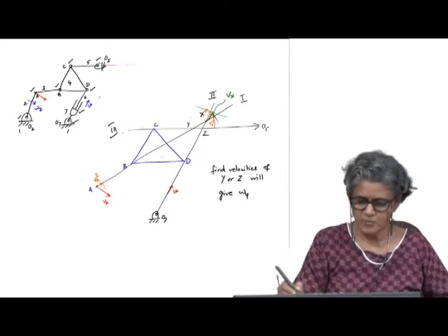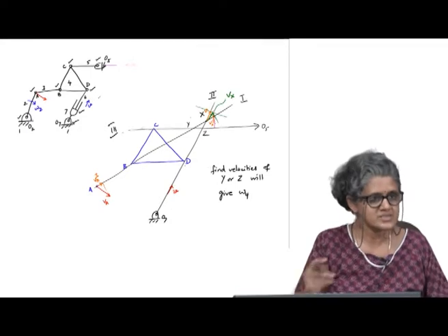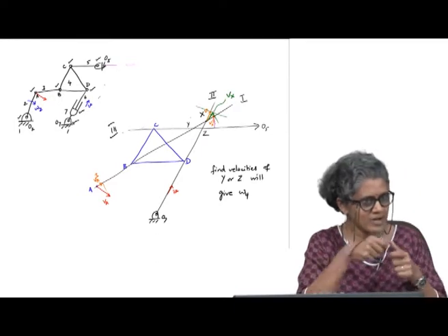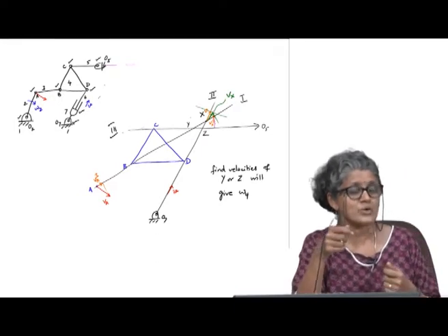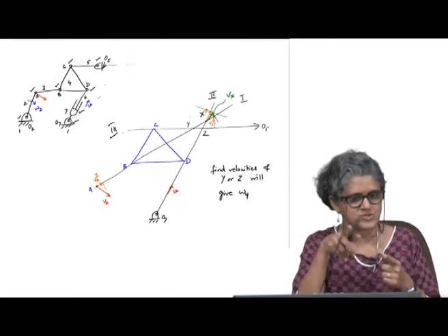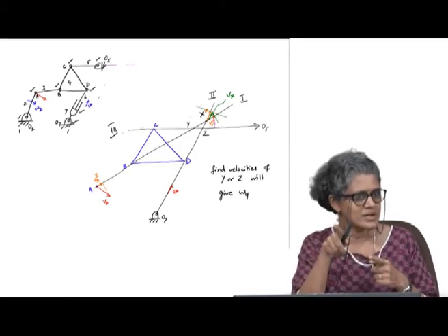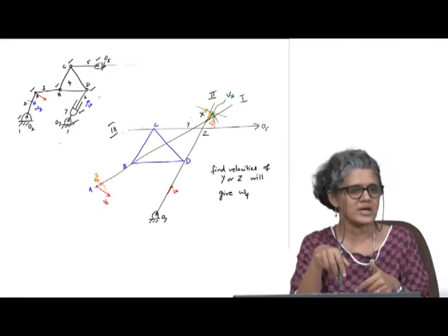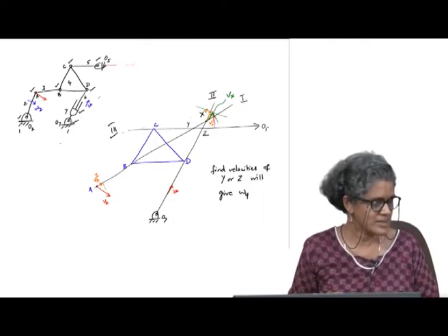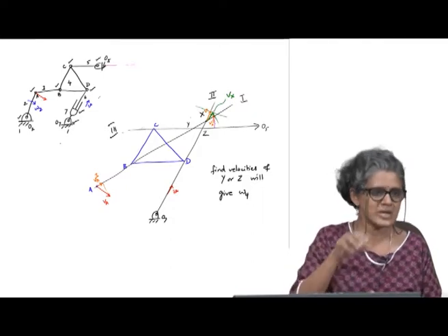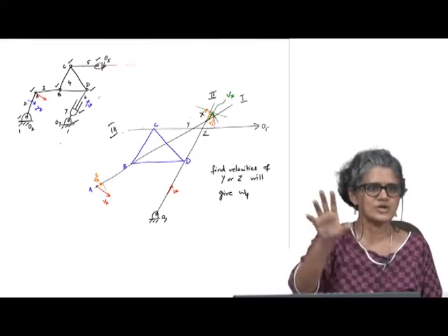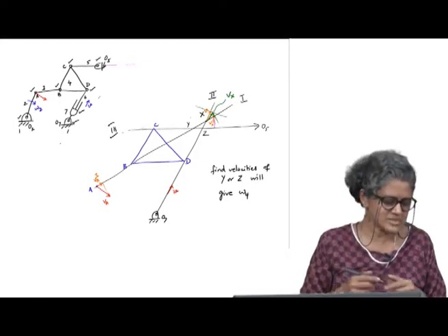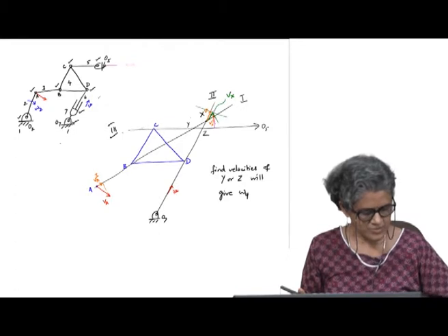So, the perpendicular component at D is not transmitted, so we are not really concerned. So, in a practical situation, this is probably what you are going to know. If you know the hydraulic actuator, you know at what speed that is operating. So, you would know that velocity along the line of action of that actuator. It is unlikely that you would know both omega of the actuator and the line, because that will typically not be an input. If this is the actuator, you are going to give it a velocity along that direction. Okay. So, that is what the auxiliary point method helps you to do.